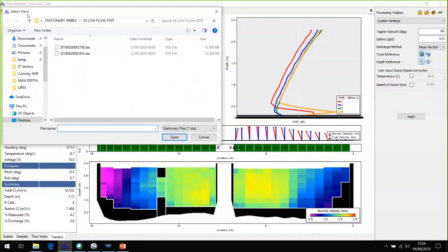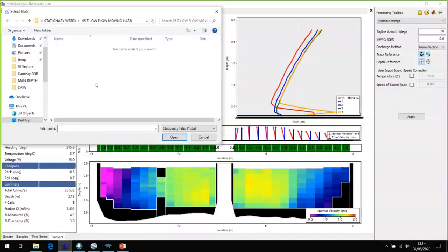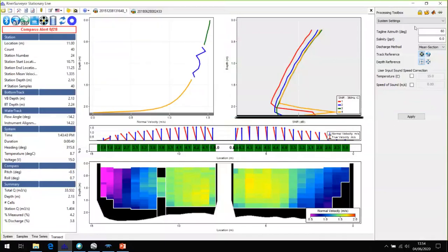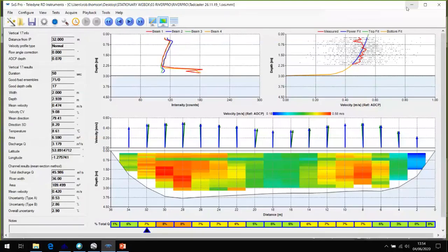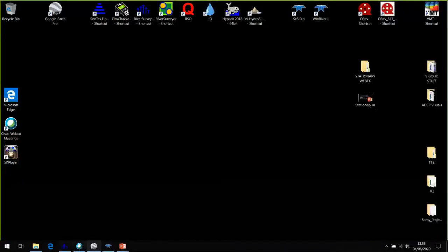Yeah, okay. I'm just having a muck about with section by section. You can bung in that good ensembles in cell threshold. I've gone up to 50 and it's still working. It's thrown out tons of my data. It's not a good move to go to 50, but all right, it was 5 for some reason. I don't know where I've got that from. That was a very useful bit of learning, because the data I'm looking at had an erroneous high velocity at the bottom, and I've managed to get rid of it. You can get that same screening.